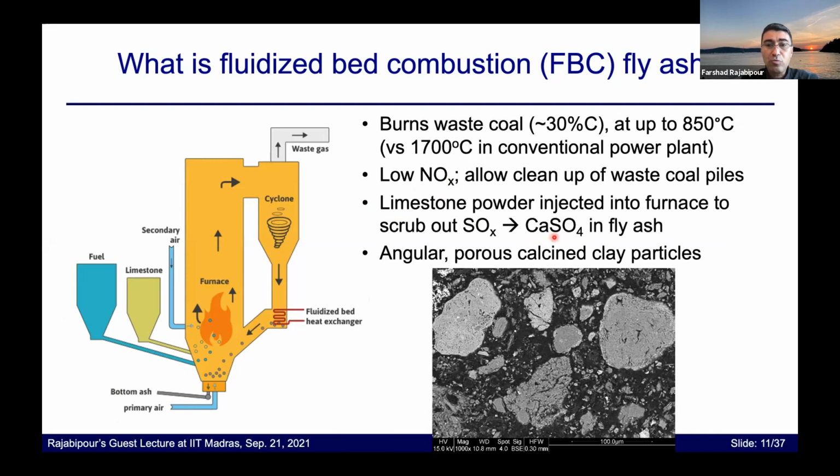The other attribute of these fly ashes is that, because of the low combustion temperature, the clay phases do not melt, but essentially they become calcined, and they retain their angular and porous particle shape, as we see in the SEM micrograph over here. And that can lead to a higher water demand, or a higher demand for water reducing admixtures in concrete.